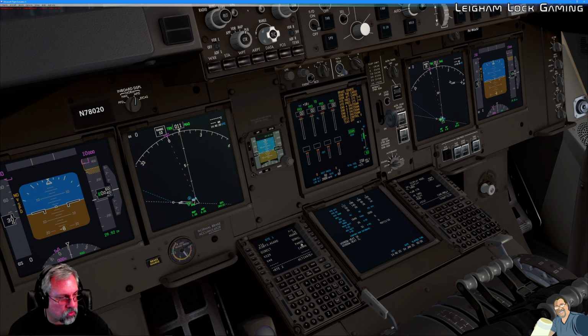Now what we need to do is work on our arrival. So from here, once we've got our last waypoint put in, from the last waypoint we're direct to JFK to runway 22 left. That's the initial runway assignment that we have. So back to departure arrival, here we have JFK. We're going to pick our arrival. And 22 left is the runway assignment we have currently according to our flight plan.